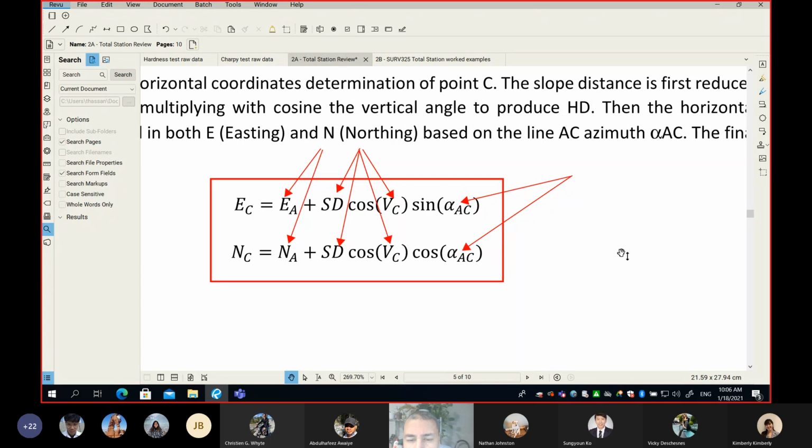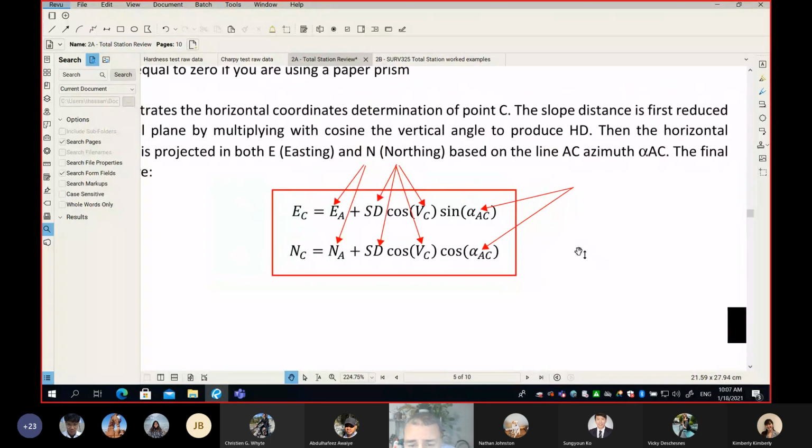However, it's pointing to the north of the site. From this point on, not before this process, we can take a reading of the total station, and the reading now has a meaning, which is the azimuth of the line. So please be careful. I want you to understand that if we are interested to find the easting and the northing of a point, backside is a must, and you need to understand that for backside, we need 2 points of known coordinates, which means 2 traverse points.